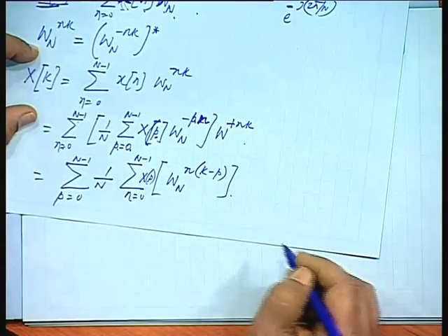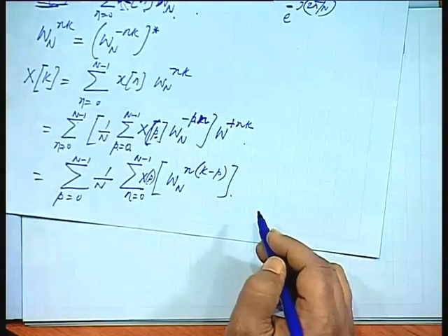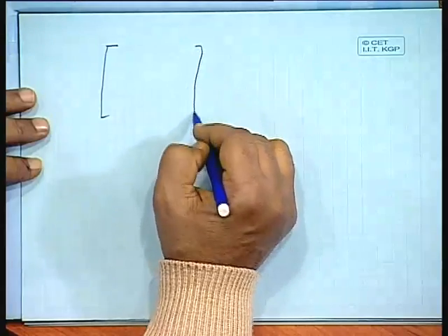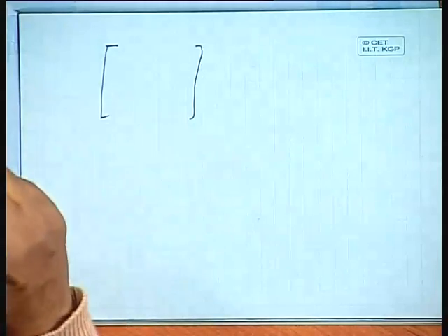Now, most of you have studied in 3-phase power systems balanced and unbalanced voltages. Any unbalanced system we can always represent in terms of sequence components, 3 sets of balanced voltages. If you remember, the transformation matrix that we used had an angular shift of 120 degrees.